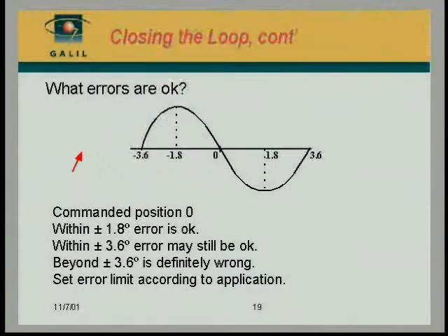Within 1.8 degrees is fine. Between them, it's up to the application engineer. And you should select that according to your application, because if you know that in your application the error is always a small fraction of a step, you could set the limit to that.